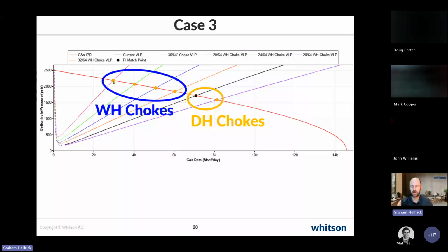And our recommendation is, if you have a wellhead choke, there's really no point in doing the complex calculation through the wellhead choke to get the bottom hole pressure, because you typically have a measurement of the pressure on the wellhead choke inlet, which is the tubing head pressure. So our recommendation is, if you have a wellhead choke, use the tubing head pressure as a pressure source, and then you'll be able to do just a simple calculation from the wellhead pressure, which is, again, upstream of the choke, down to the bottom hole pressures, and that's the recommendation.